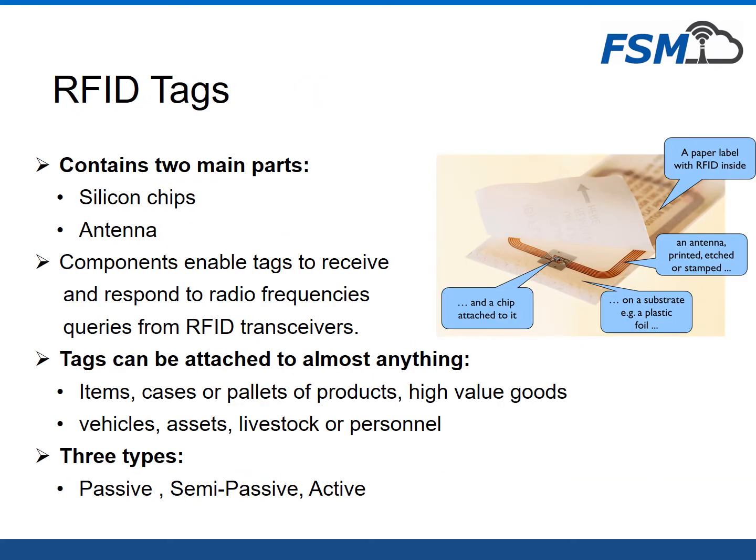Tags, as you would see, sometimes are disposable tags in high frequency ranges, but industrially speaking, most of the tags are reusable ones in proper Teflon or a PVC coat. Sometimes on metal carriers, again, the engineering is predefined on what kind of ranges, what kind of signal attenuation, what kind of metal interferences happen.